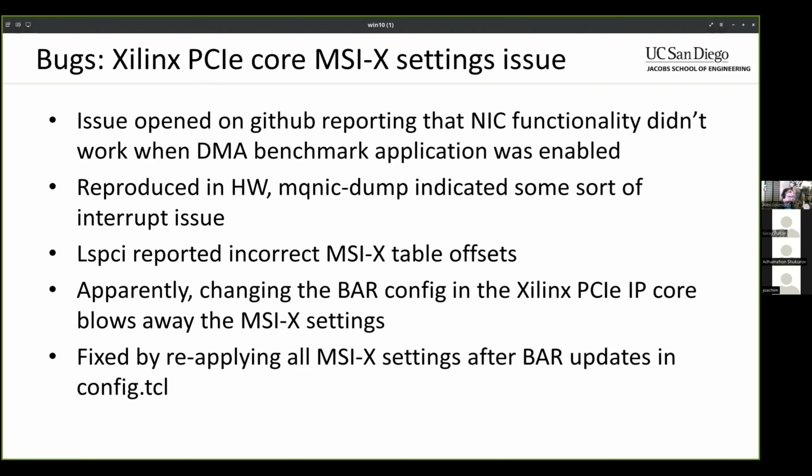And that one, mainly it sets a bunch of the top level Verilog parameters that propagate down into the design, but it also changes some settings on the PCIe IP core, so that those settings match. So if you enable the application section, then it will turn on the bar. If you set the application bar size, it sets the bar size, and it also sets the parameter informing the design of what the bar size is. And then that sets the address layout and whatnot.